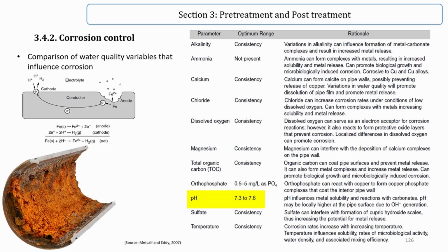That increases acid concentration. High levels of alkalinity over 150 mg per liter as calcium carbonate have been observed to cause increased corrosion of lead, copper, and zinc. Natural salts such as chloride and sulfate can act to increase corrosion rates, particularly at low oxygen concentration. Oxygen can induce and promote corrosion reactions, particularly under elevated temperature and pressures.